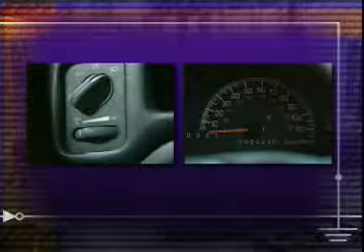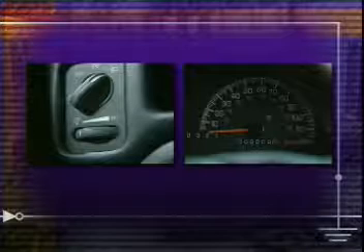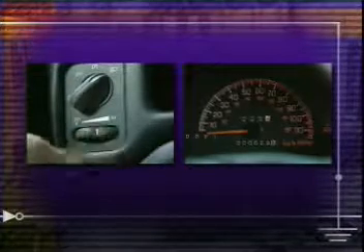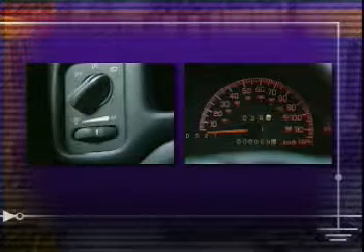A common series parallel circuit is used in the automobile in the dash light dimming circuit. The dimmer is a type of variable resistor called a rheostat and is wired in series with the bulbs that are wired in parallel with each other. As the resistance of the dimmer changes, the bulbs will all increase or decrease in intensity at the same rate.